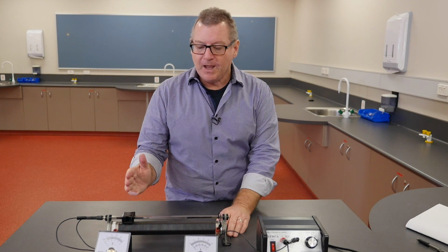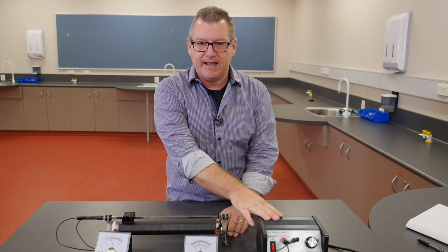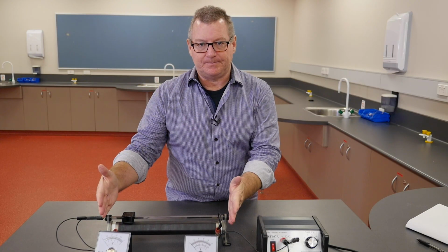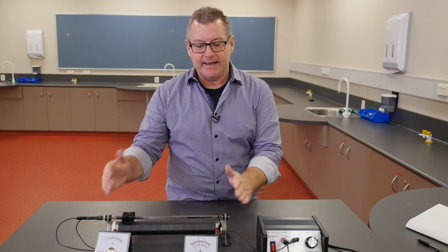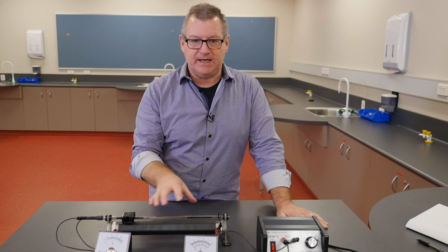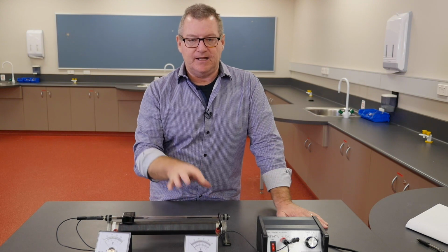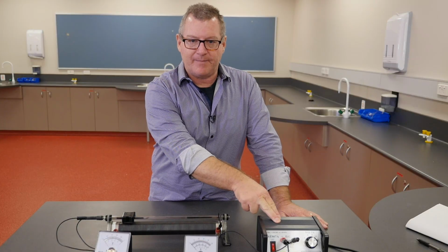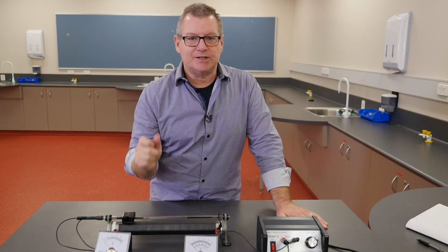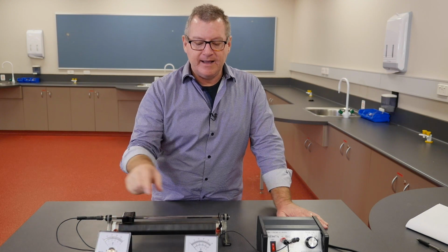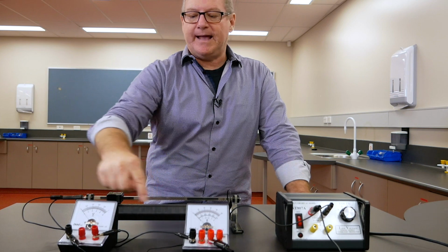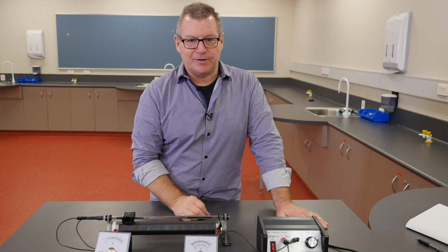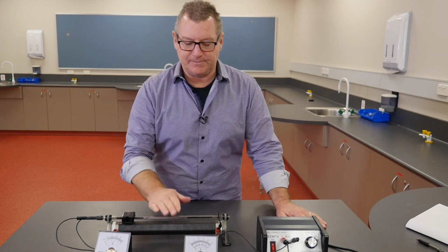So we will change the voltage using our power supply. We will read the voltage. We've placed a voltmeter across this to know the voltage that's dropping. And because everything else is wires and meters, nothing else should be a resistance that causes voltage to drop. So the voltage we read on our voltmeter should be close to what's coming out of our power supply. So we'll change the voltage from the power supply, read it on the voltmeter, and then the current is flowing through the ammeter and around through the circuit, and we'll measure the current as it's flowing. And then if we graph those two things, we can find out the resistance of this particular resistor.